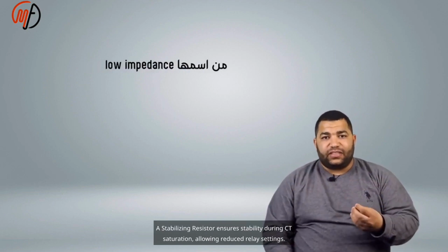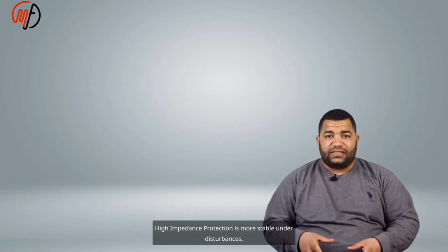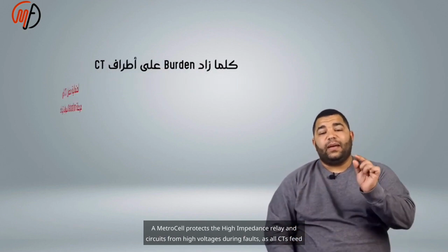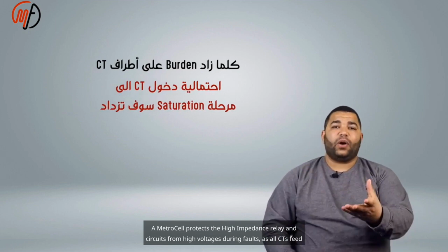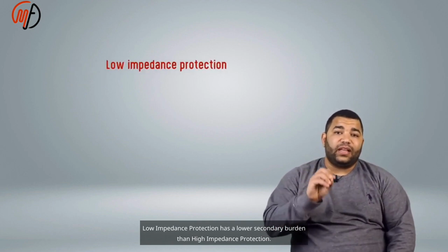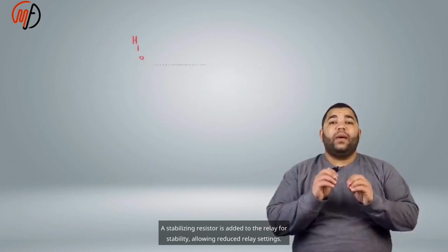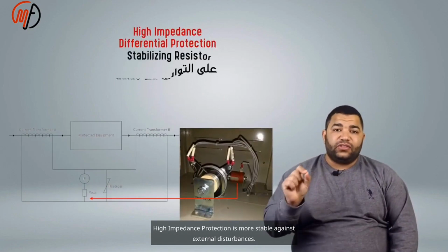A stabilizing resistor ensures stability during CT saturation, allowing reduced relay settings. High impedance protection is more stable under disturbances. A metrosil protects the high impedance relay and circuits from high voltages during faults, as all CTs feed it with large current. Low impedance protection has a lower secondary burden than high impedance protection. A stabilizing resistor is added to the relay for stability, allowing reduced relay settings. High impedance protection is more stable against external disturbances.